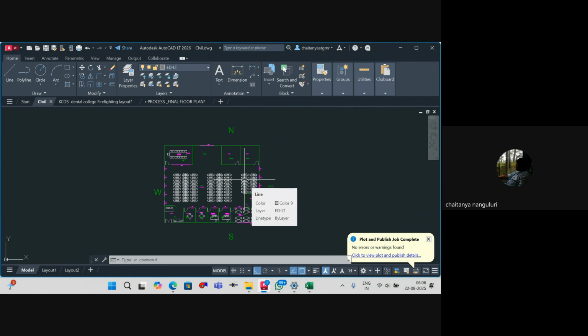Number two, we'll always consider 4 p.m. in the evening, which is generally the peak for heat accumulation inside the room space. The reason we say 4 p.m., unless your building is probably with glass, is two things. First and foremost, 99% of the time, whether you have block work or glass, 4 p.m. is a worst case situation. When do you think you have the highest temperatures in a day? At what time? Afternoon, 2 o'clock like that.